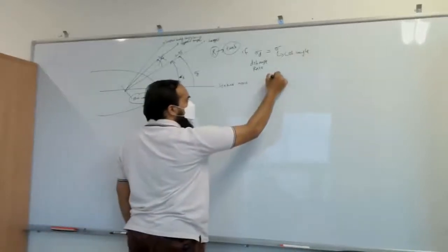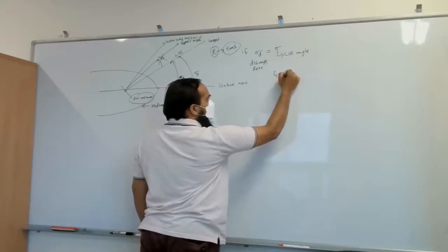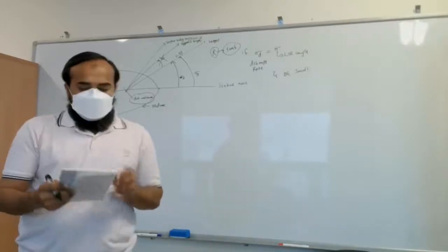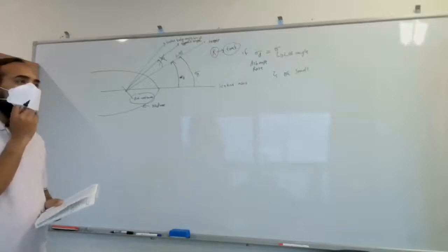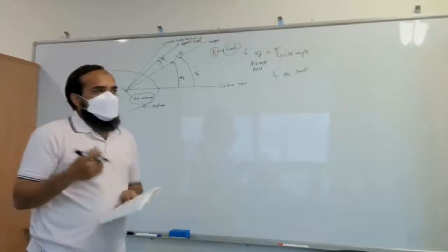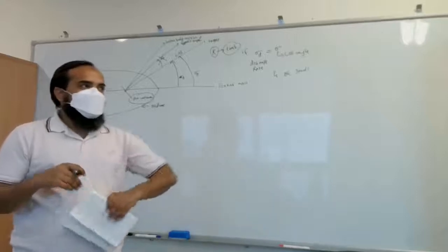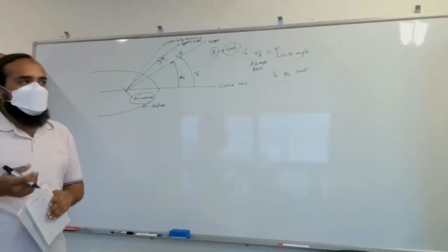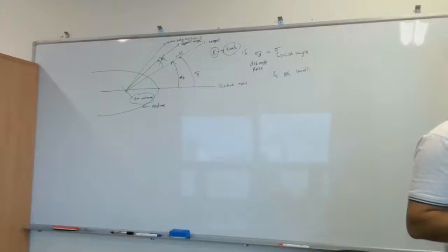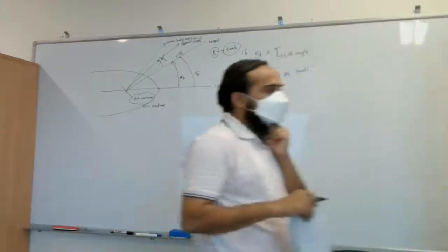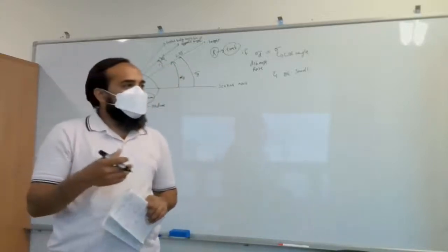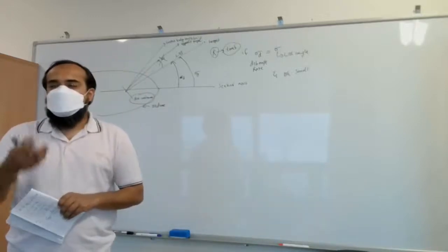So if we make the time constant of the seeker small, then the seeker dish angle and the line of sight will be approximately equal. So you have to make sure the time constant is adequately small, capable of tracking a highly maneuvering target. And you have to keep in mind that the increased miss distance associated with the radar guided air defense missile can be blamed on random reflection error. So if there is a random reflection error, then we can increase the miss distance.